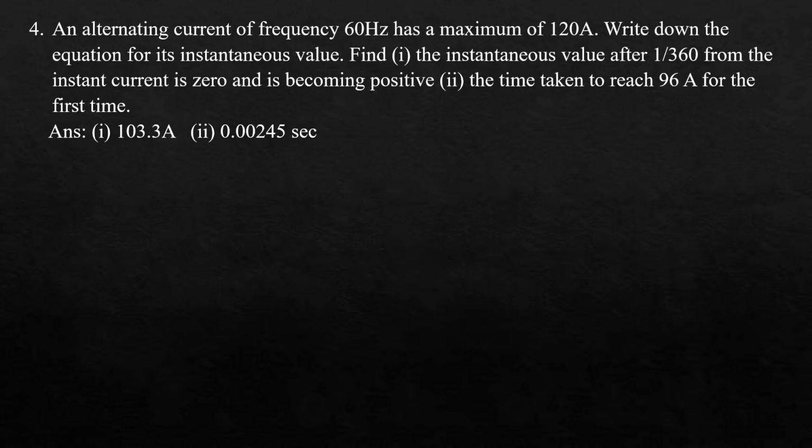Now I'll put this in the calculator and find out the value. 120 into sine, 120 shift pi into 1 by 360 into 180 by shift pi, and bracket close. I've got 103.9 amperes.